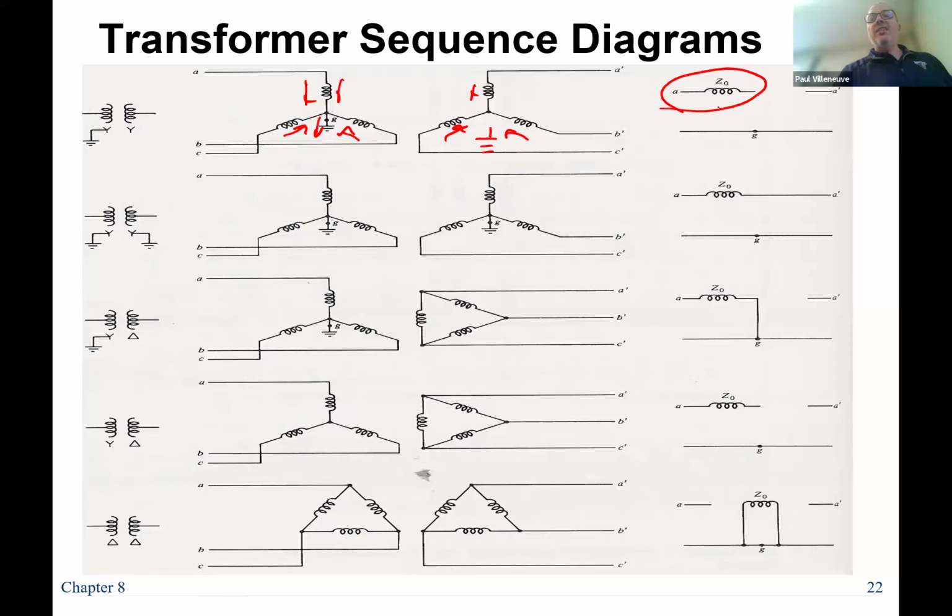You can show the impedance of the transformer connected to the winding that has the ground, but no current can flow through there. Okay? This is a block. Doesn't happen. And I've never personally seen a grounded Y and then non-grounded Y transformer. I've just never seen it. These are all over the place on distribution systems. And what I see is current flowing through here. You can flow through here, right? Because this current goes here and that current goes through here, but it doesn't return back. So that current just blows through and continues on to wherever the load is.